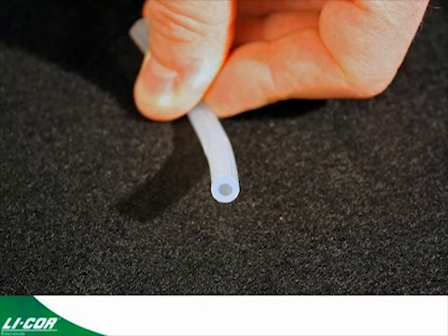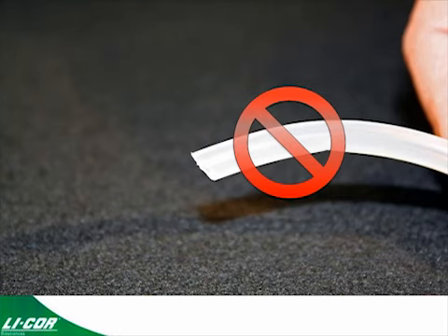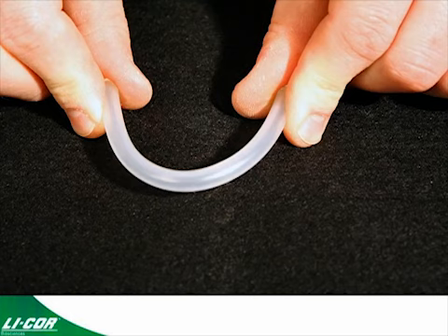When cutting the tubing, you want to make sure that you have a nice, smooth, square cut on the tubing. Deformed tubes like this or ragged cuts like this result in leaks around the tubes and the hose barb connections. The cut should also be perpendicular to the flow path, unlike what's demonstrated here. When you have an angled cut, as this demonstrates, that does not match up to the hose barb, potentially leading to diffusional leaks. When bending your tubes, care should be taken to ensure that you have nice, gentle bends.